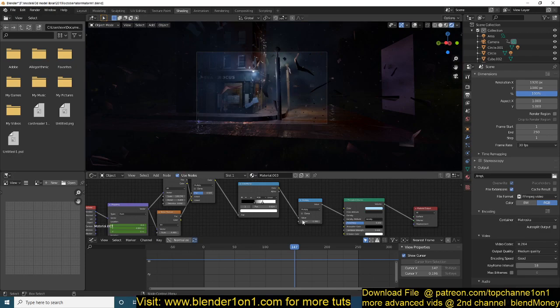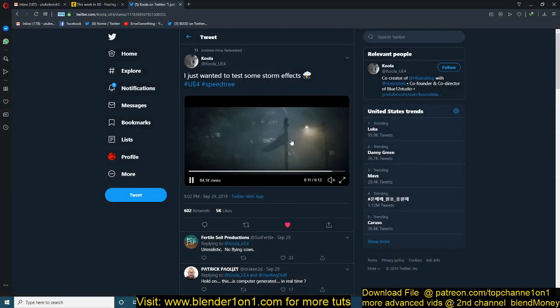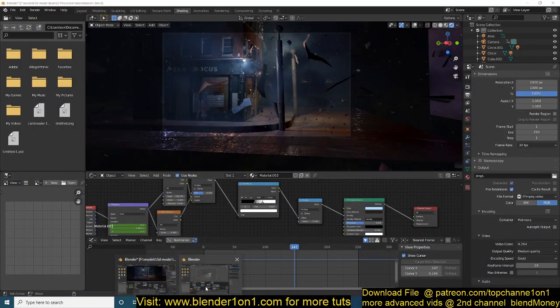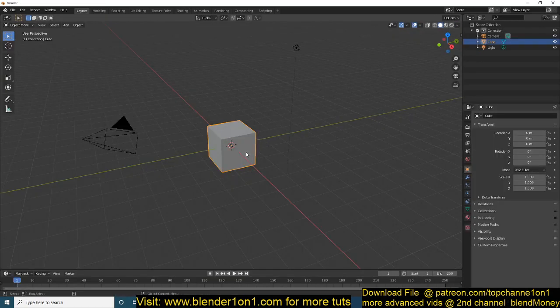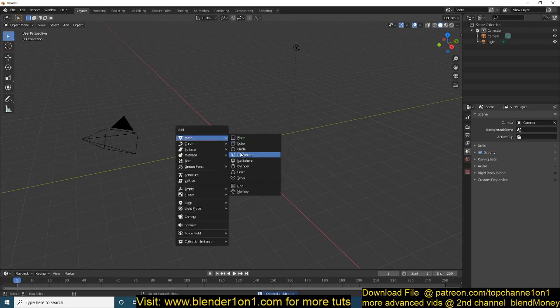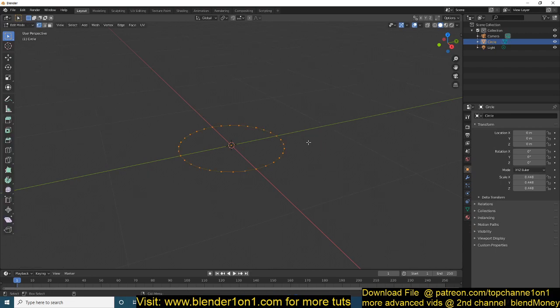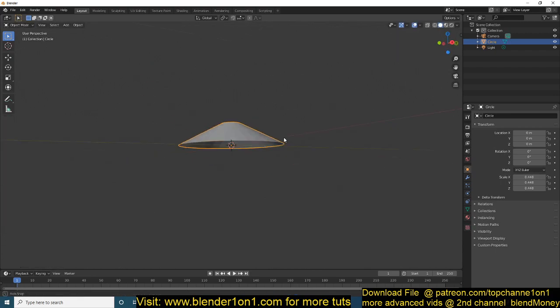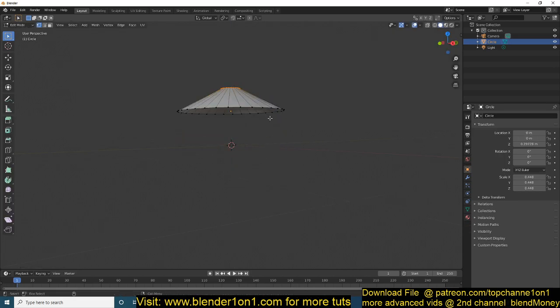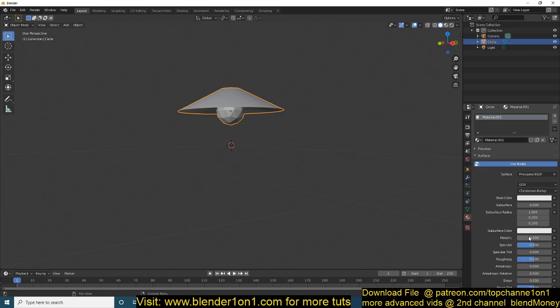Now the other part is making this light swing, because that's one of the hardest parts. So what I did here, let me just open a new blend file, get rid of this. I just used the rigid body system. First you have the lamp, which was very simple to make, so I just added a circle like this. F, insert, push up. So that's our cone, and now we just need the lamp itself. You can use an icosphere, scale it down, and you would give it a different material. So let me just do that. This would be metallic.